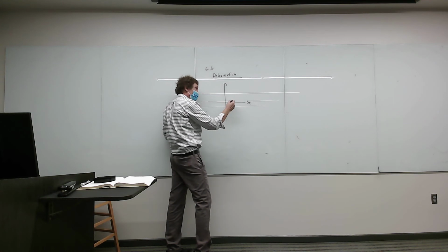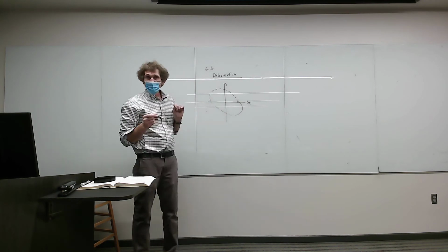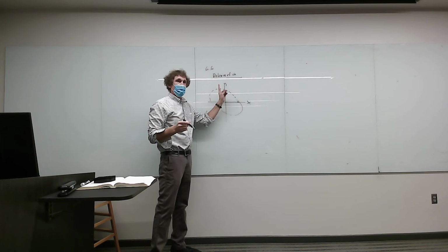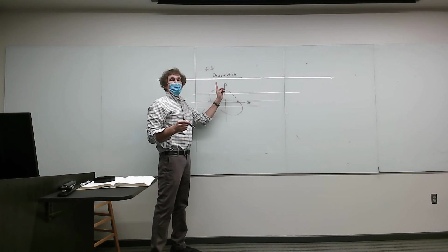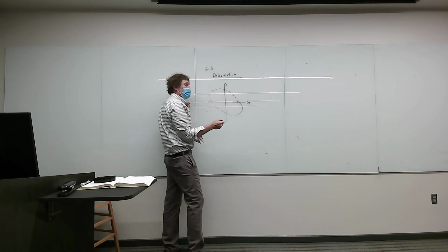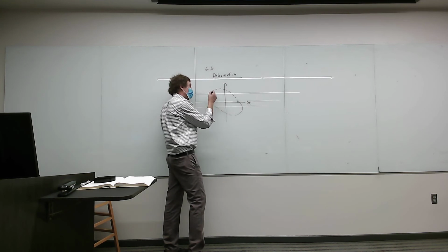But another one would be that the electric field itself would trace out something that is not a circle but an ellipse. They should make sense to you, right? That's when we would have an electric field in the Y direction of different magnitude than the peak electric field in the X direction. Follow me? Then you would trace out an ellipse and what's called the actual tilt angle of the ellipse.